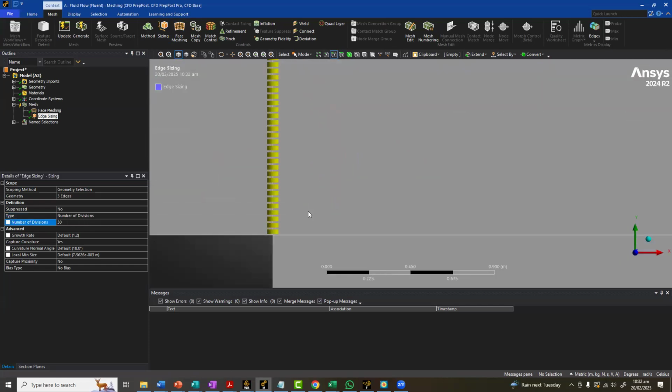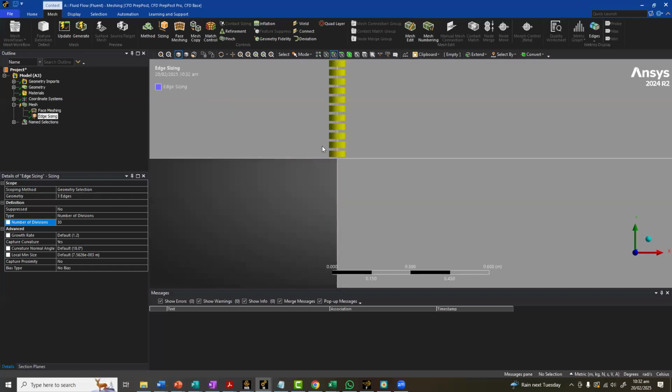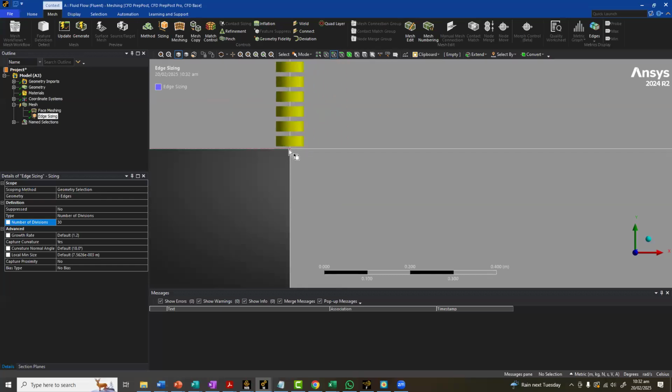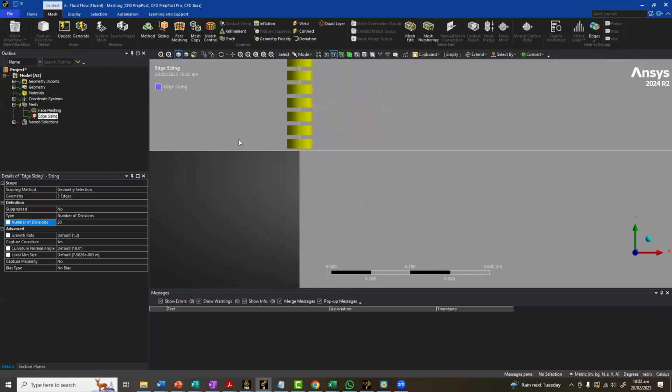Okay. But I need the finer mesh towards the wall here because the flow will separate from this point. So we need the finer mesh here, not on the upper side. So I just need a fine mesh over here. So I will use the biasing, for only one side. And biasing factor of 30, this is enough, I think.